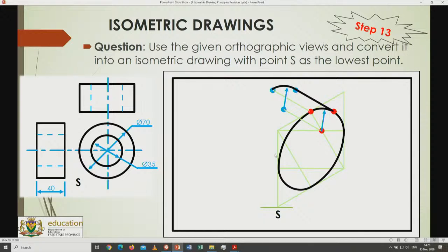Now I think you can imagine if this goes 40 deeper in for the arc over here, the same will apply. I already got my 40 inwards there. This is my second point, so I'm going to go 40 millimeters inwards to find that point over there, and I'm going to go for this intersection point 40 inwards to find it, which are those points. Take my compass, the same dimension I've used for this circle. I'm just going to replace the sharp needle end to that point, and I will be drawing the arc from there up to this point over here. And then for this little circle over here, again I will use this last point, and then from there the intersection points and the start position, 40 outwards, and I can complete the rest of the lines of what you see over there.